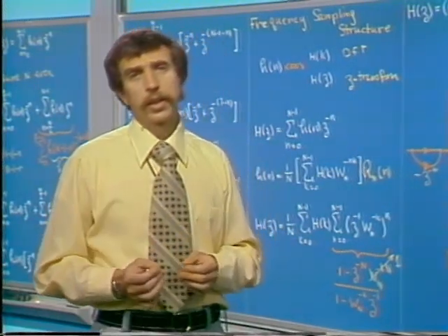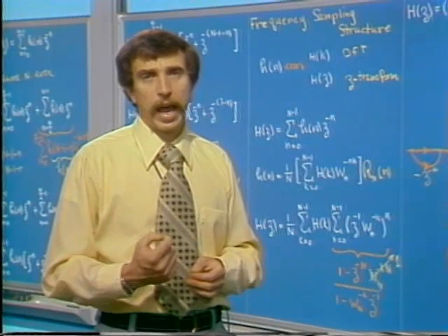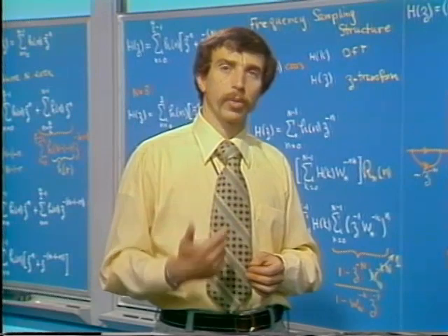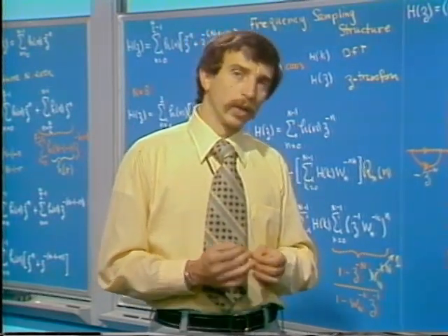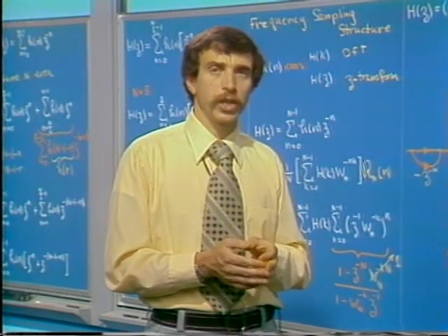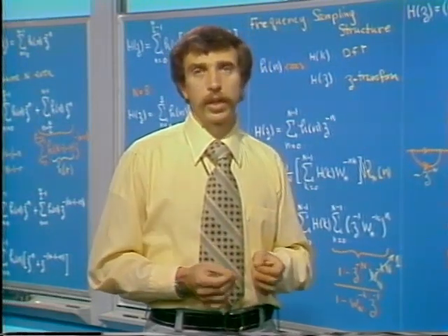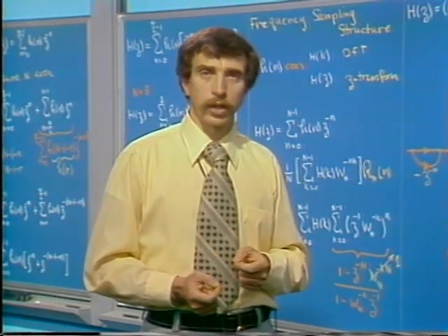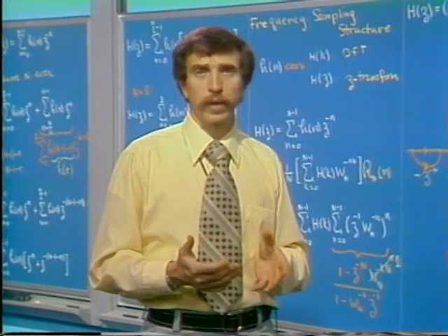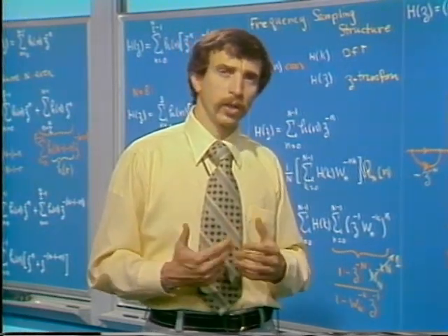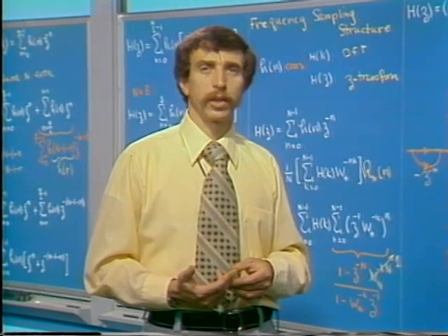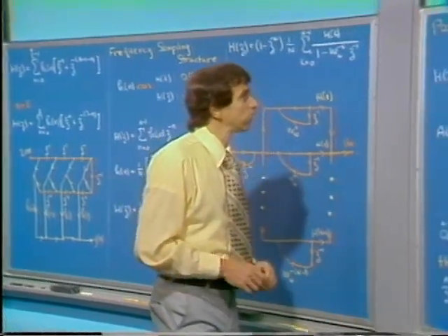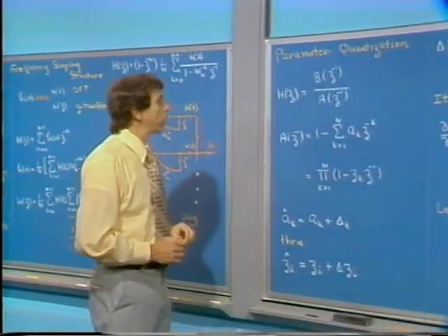And the second thing is the fact that coefficients have to be represented in finite register length. That is, coefficients or parameters have to be truncated. What I would like to do in closing the lecture is just briefly give you a glimpse into some of the issues of the coefficient or parameter quantization, and not delve in any more detail into the relatively complex issue of finite register length effects. But let's focus just a little bit on the effects of parameter quantization.